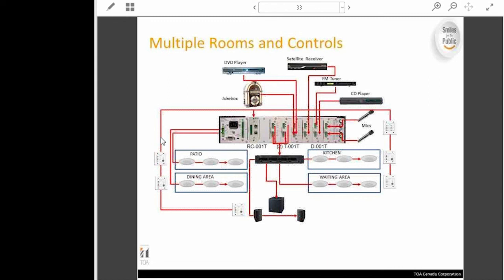Now we have volume control and preset stations in each of these. So this is all ZM9014 control stations in the lower portion of this, with the 1 8-button station activating presets. And we do have a master control at the bottom that is handling some preset control and volume control for the master of the system. That would likely be close to the head end, whereas each of the other remote panels would be set up in their specific rooms.